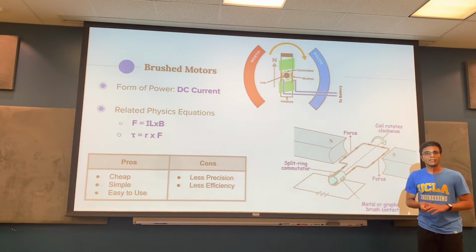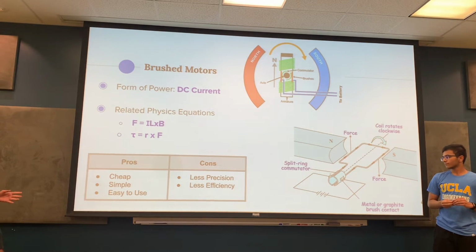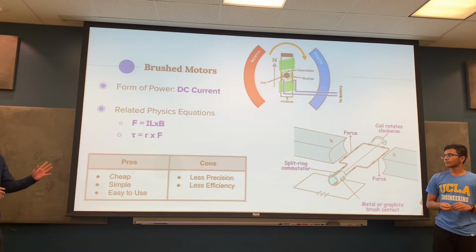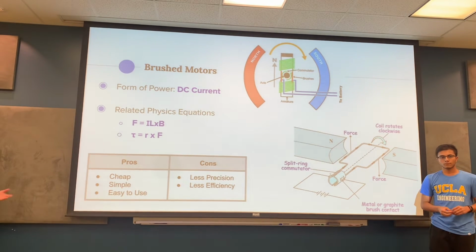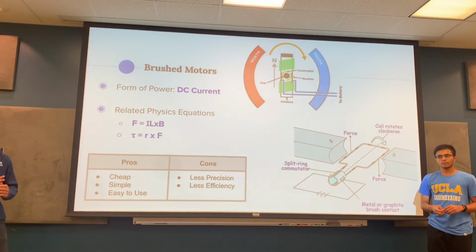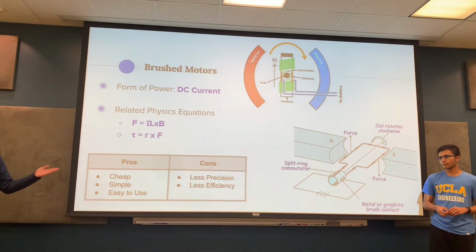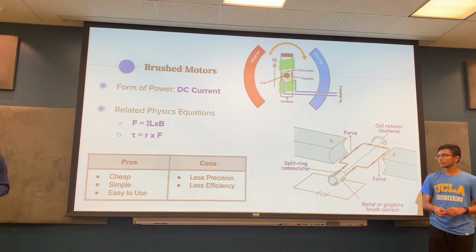The most important thing to remember between these two types of motors is that the shaft of the brushless motor is the permanent magnet, with the electromagnetic coils helping it spin and changing the magnetic pole. In the brush motor, the shaft is the electromagnet which changes the poles, and the permanent magnets are on the outside.